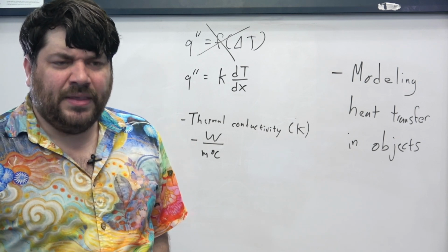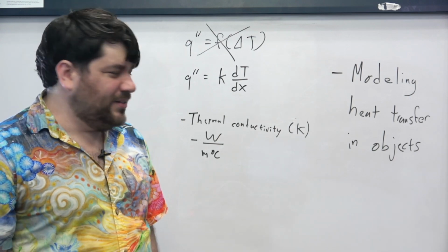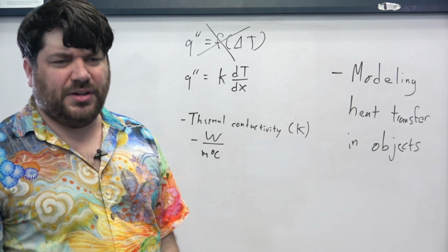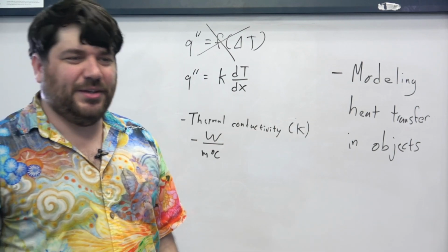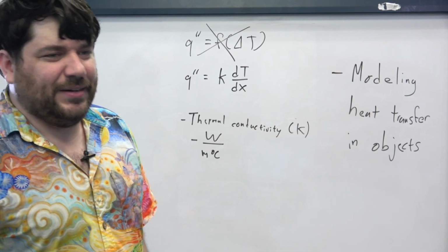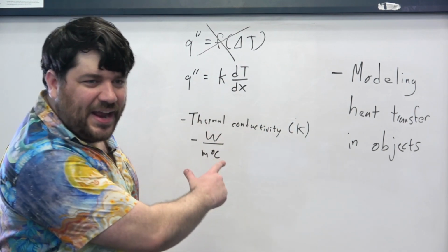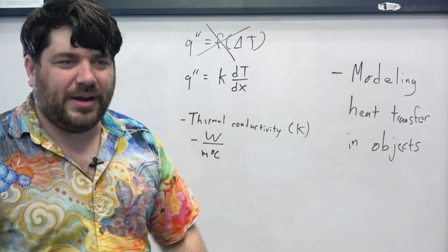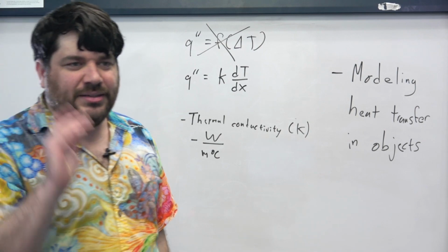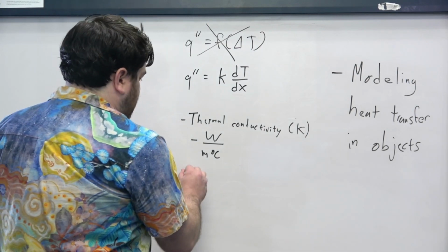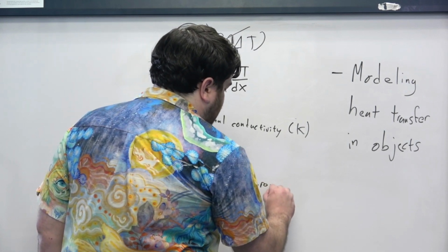So yeah. But that being said, that doesn't mean that the thermal conductivity can't be a function of a bunch of different things, right? Thermal conductivity is a function of temperature. It's a function of all kinds of weirdly unrelated material properties that you would think don't affect it, but do, right? And so it's the same weird thing. We're not going to have a nice theoretical mechanism to pull what k is from first principles. We just measure it from experiment and say, off we go. So we're just going to say that this thing is approximately a material property, okay?